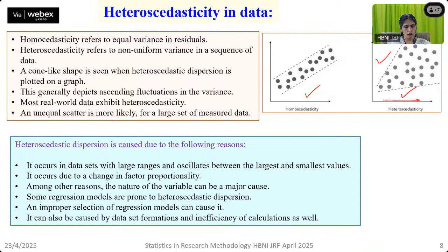If you presume a particular linear relationship, it may not be valid for a larger range. Rather, apply it to small portions and get quality data. And if there is a proportionality variation in the instrument signal as we go to a higher range of input parameters, the onset of fluctuation will be visible. So in that case, go for a narrower range and get rid of this problem.